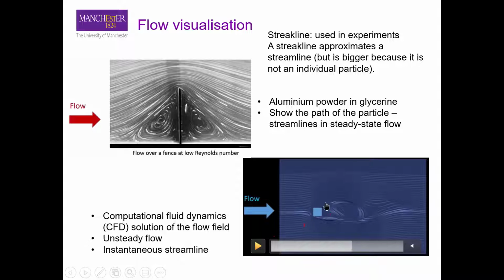Okay, so because of these streamlines hitting this object, you have a change in velocity, and as such you have a vortex formation. And after a certain time of this vortex formation, what we call vortex shedding, it means that you don't have a vortex anymore, but you have how the velocity is changing as the fluid is moving through this region.